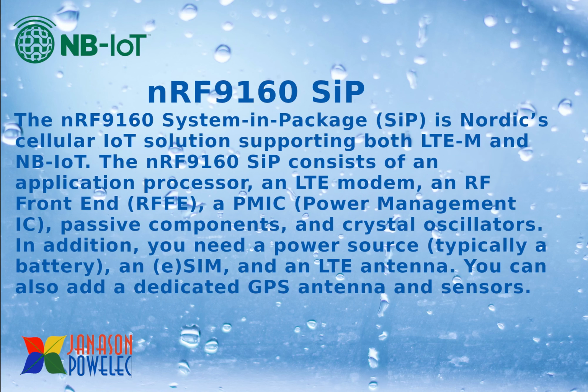nRF9160 SiP. The nRF9160 system in package is Nordic's cellular IoT solution supporting both LTE-M and NB-IoT. The nRF9160 SiP consists of an application processor, an LTE modem, an RF front end, a PMIC, that is power management IC, passive components, and crystal oscillators. In addition, you need a power source, typically a battery, an eSIM, and an LTE antenna. You can also add a dedicated GPS antenna and sensors.